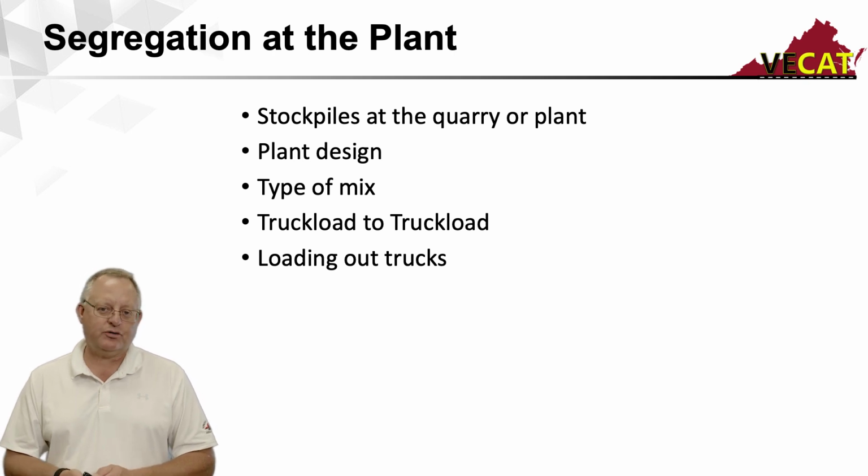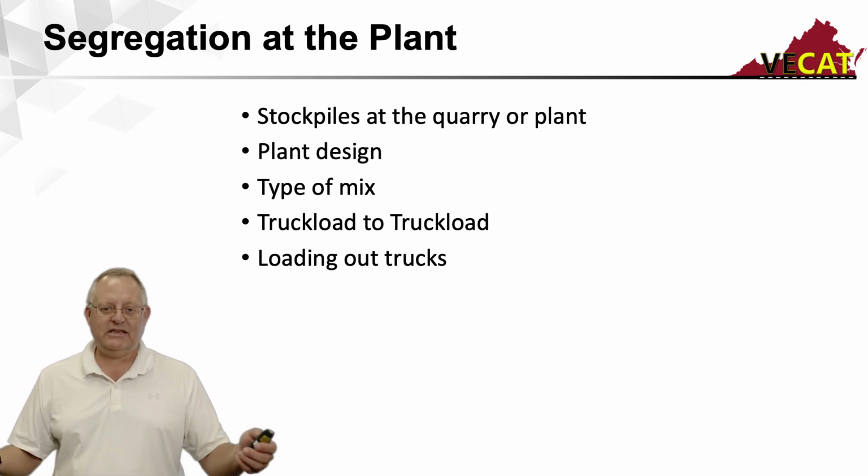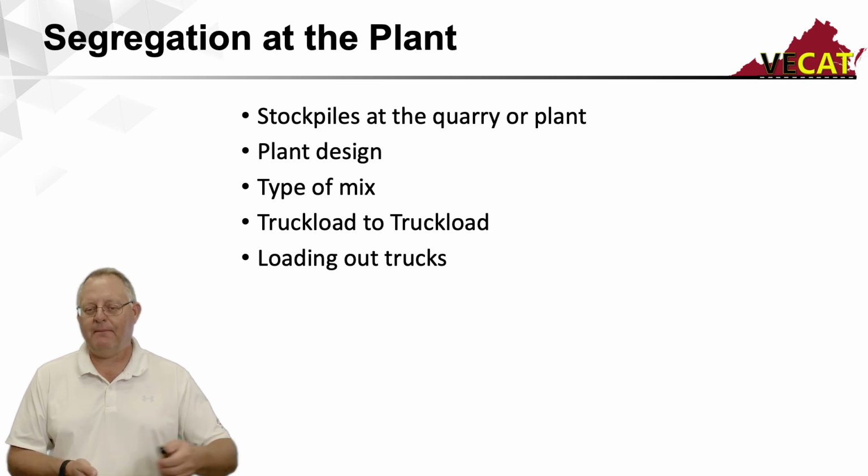How we're loading out the trucks. Are we doing proper loadout? Are we doing 3 drops? Are we dropping it at the front, back, middle? We're doing 1 continuous dump. How we load these trucks out will impact segregation within the truck.